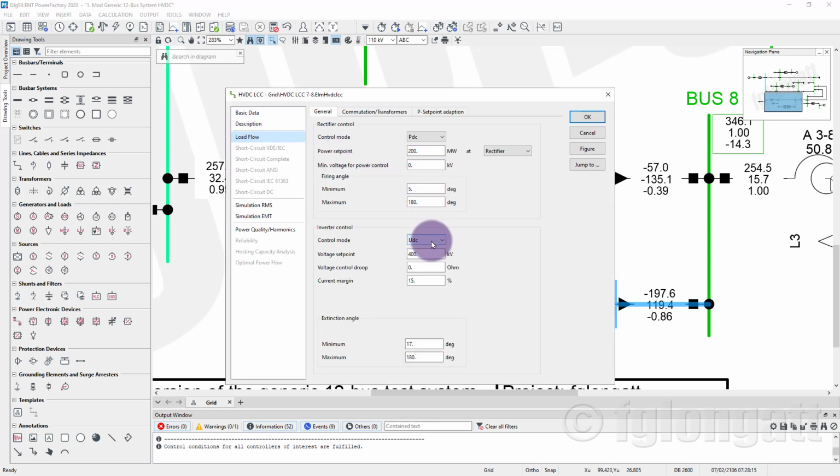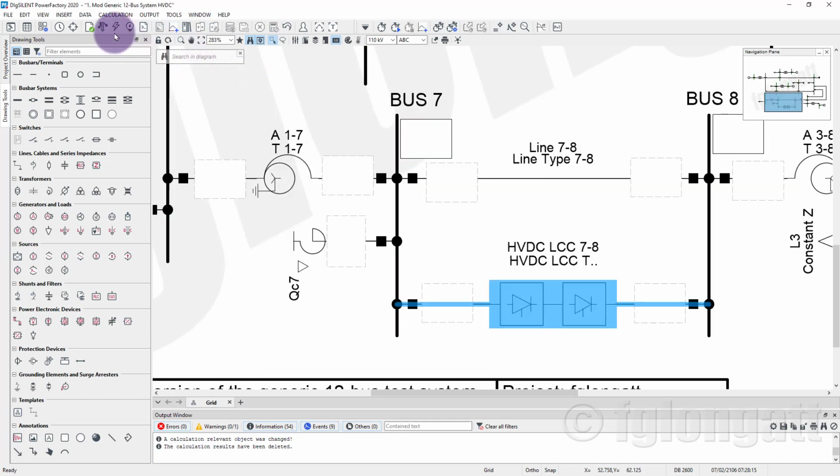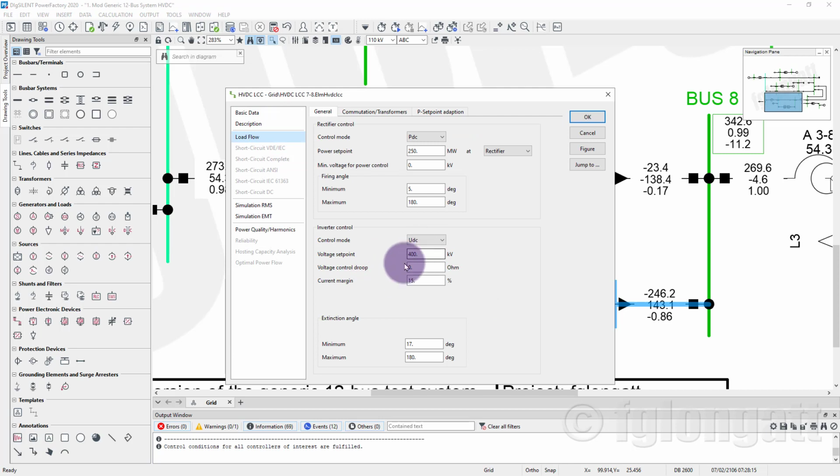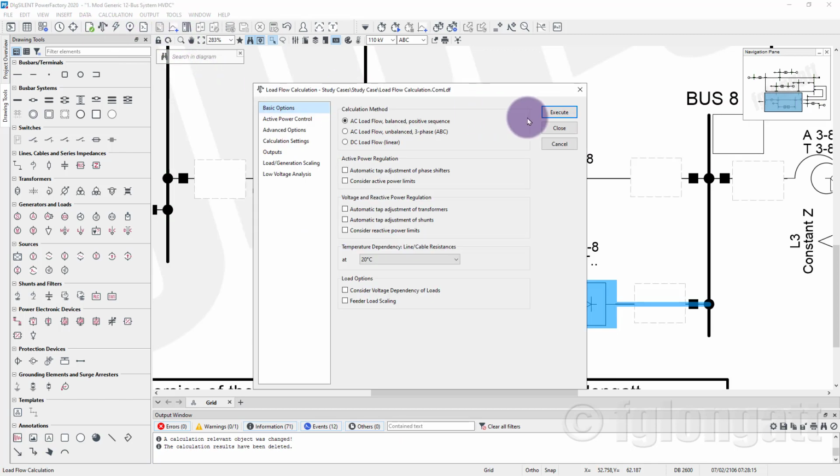Now, a new try. Now let's go for 250. As you can see, the voltage on the AC side is starting to go down, and we reduce the power on the AC line a bit more. However, something that you need to take care about is the reactive power moving through the line, okay? You can minimize the active power, but what's happening if we change the situation and go back to 100 megawatts? Right now we are using 100 megawatts.